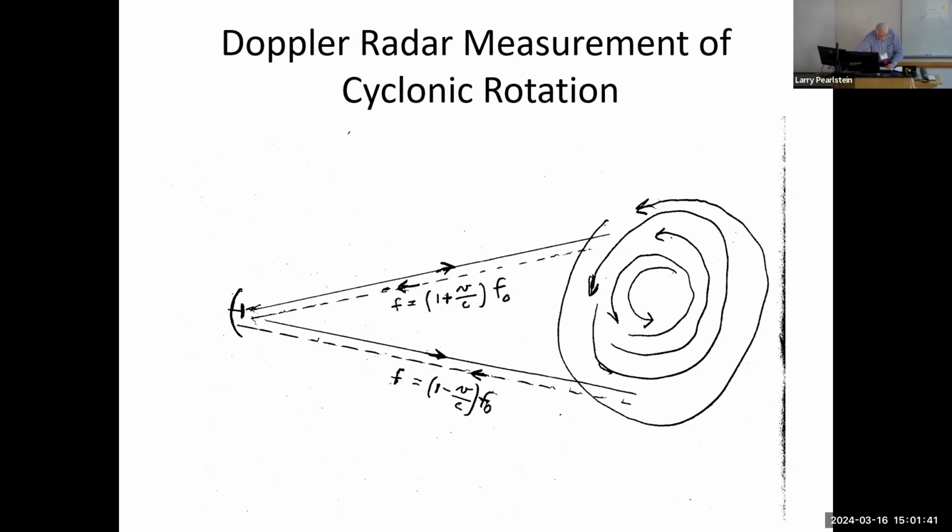We now measure with what's called an NDIR cell, non-dispersive infrared cell. Non-dispersive means you're not using prisms and gratings as in an actual spectrometer. And you exploit some of the same wavelengths that CO2 absorbs, which cause it to enhance the greenhouse effect. You're catching it by its own trick.